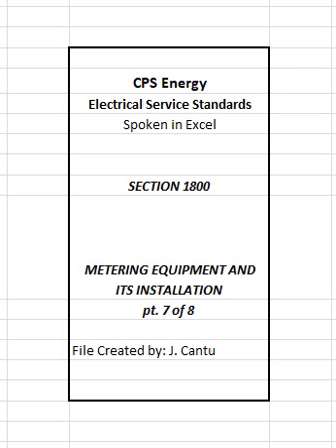1808 7 Identification of group metering and service equipment. Where meters are grouped, customer shall label the service equipment for each tenant with their specific service address to include suite numbers where applicable. 1. Where electric meter rooms are approved and used by customer, address markings also shall be added on instrument transformer and meter enclosures to readily associate with customer's service equipment.